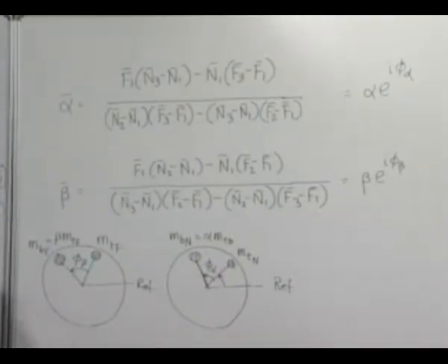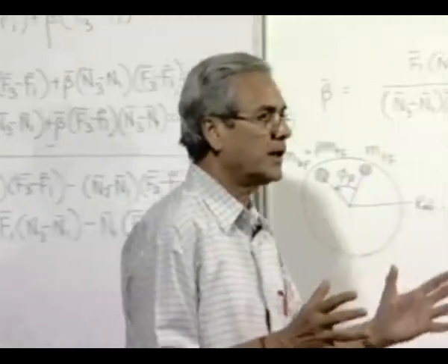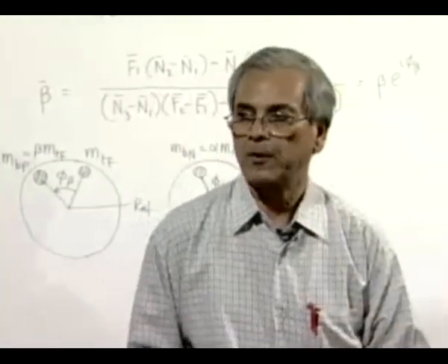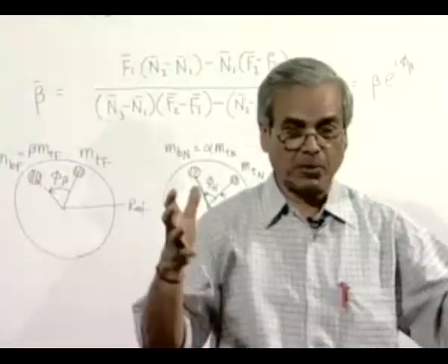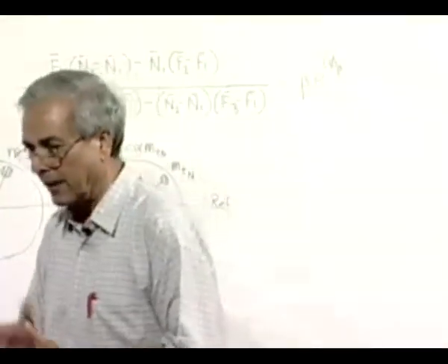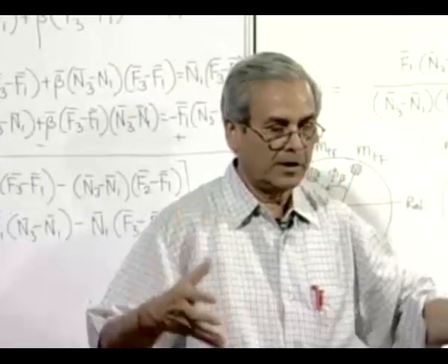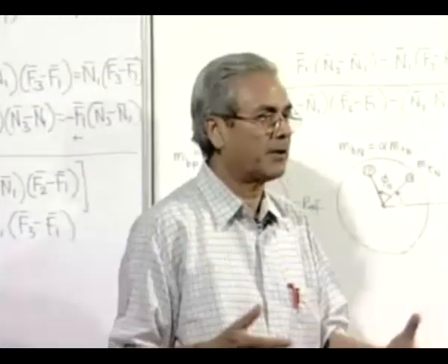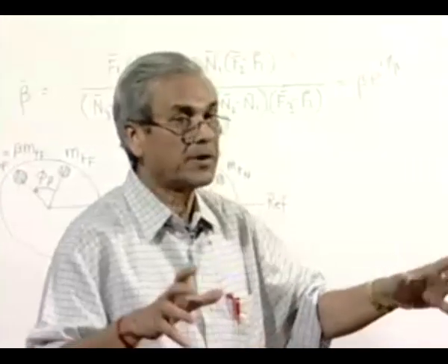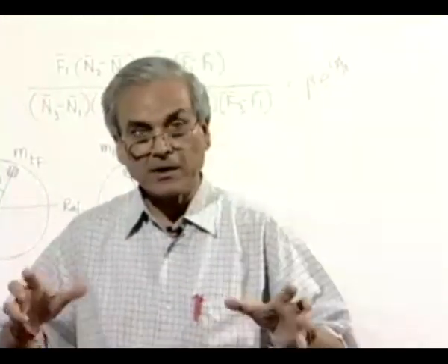The last thing which I would like to mention briefly is that so far we have considered balancing problems where all these objects or bodies were perfectly rigid. But in an actual practical situation, it may happen that a rotor may not be perfectly rigid and it may have some significant amount of deflection or elastic deformation.